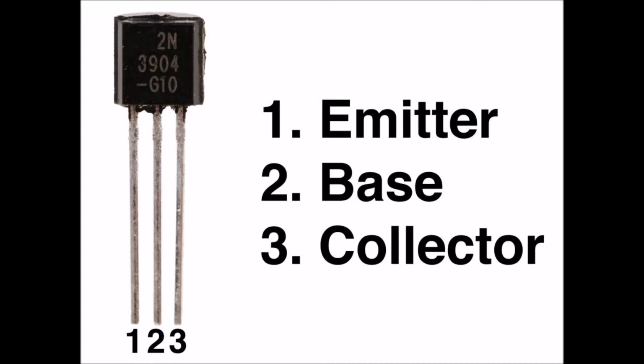Figure 22.3a shows a dual diode NPN transistor model. The base is at the connection point between the two anodes. The cathode of one diode forms the device's emitter, while the cathode of the other diode forms the collector. Figure 22.3b shows the equivalent real-world NPN transistor circuit.